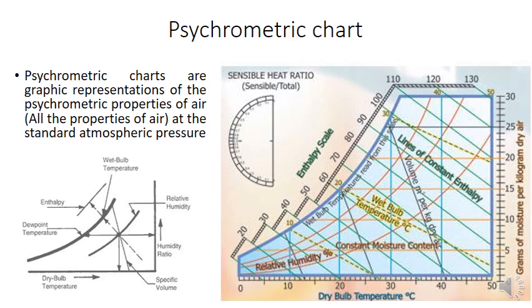Now there are a few vertical lines as well, and these vertical lines represent the simple dry bulb temperature, which is your x-axis value. So dry bulb temperature, humidity ratio, relative humidity, and enthalpy values are these lines. One point is left, which is basically the dew point temperature.